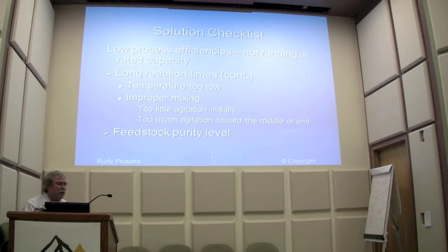Could be improper mixing, and that could be either too much mixing or too little. Part of the problem is that initially the oil, the methanol, and the catalyst don't want to mix together. So you have to really beat the heck out of it, shake that bottle up a lot, whatever you want to do, but you have to mix it very much to get it to start to mix together.